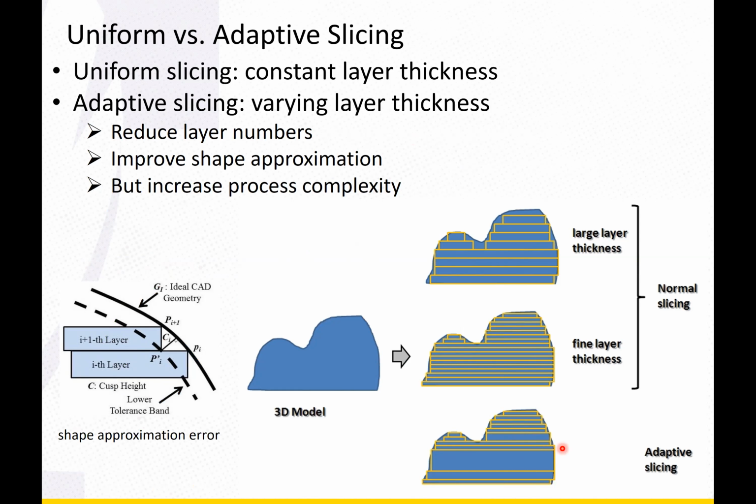Basically, although in the computation it's a perfect triangle, in the FDM process the material near the boundary over here is not a perfect triangle, right? It's not a perfect triangle. So if the thickness becomes bigger, well, I didn't test this kind of adaptive slicing on my machine, but I assume there will be some difficulty maintaining the shape of a perfect triangle.